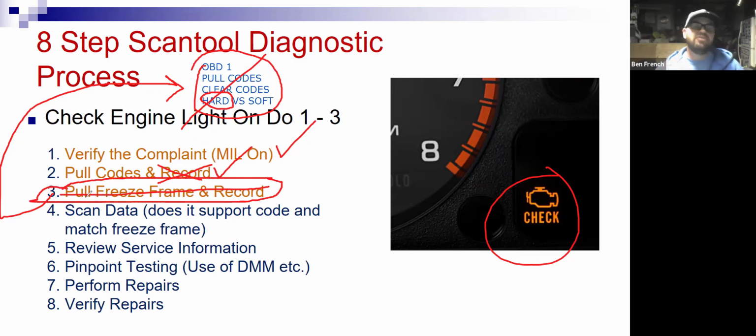Oftentimes, we'll not only lose the freeze frame data, we'll lose all the monitors. So those all get reset, and we lose a ton of diagnostic information. I don't clear the codes until after I've done my repair and I'm feeling pretty good about that repair. I clear the codes and then I go for my test drive. So right here, that is where I clear the codes.